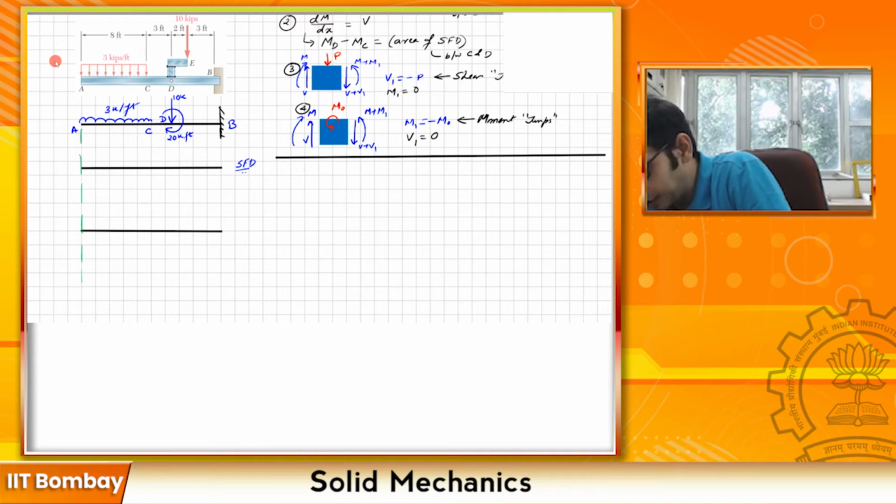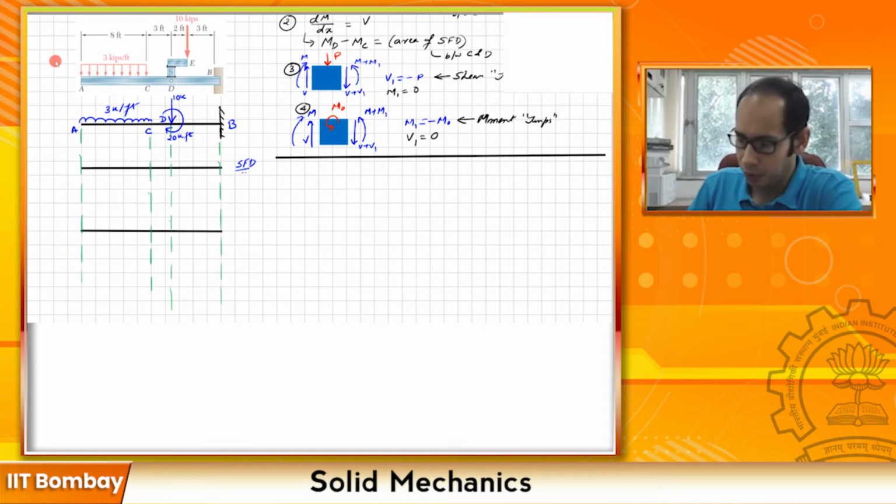One guideline I take is wherever you have discontinuities, or the load ends or the load begins, and around those points. So I have these A, B, C and D. Right, so again focusing on the shear force diagram, this is my A, this is C, this is my point D, and lastly I have this point B over here.